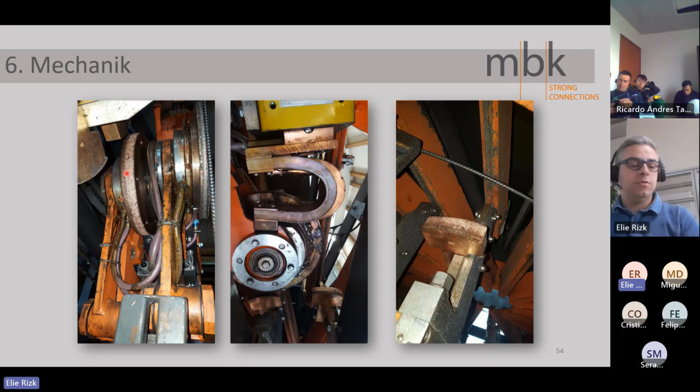You don't have black dots on the contact roller or on the welding roller, and it is well cleaned, because after some time you will have some residual from the metal. So after time you have to clean it, otherwise you will face some issues during production with welding.